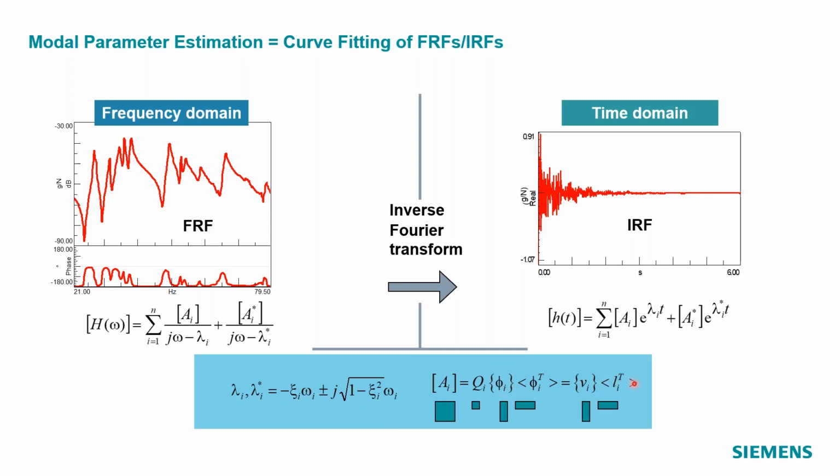There is a second part to this equation, because typically we don't see the full mode shape as a second element. We have a mode shape and we have a participation factor. That's because we typically don't measure a full square matrix of frequency response functions. So when you have 100 accelerometers, you're not going to use 100 shakers, for instance, or when you hit a structure at 100 locations with a hammer, you're not going to use 100 accelerometers, but only a few. And so this matrix is not square, and that means that the mode shape is the most complete vector, but the participation factor is only the mode shape at the locations where we do excite the structure.